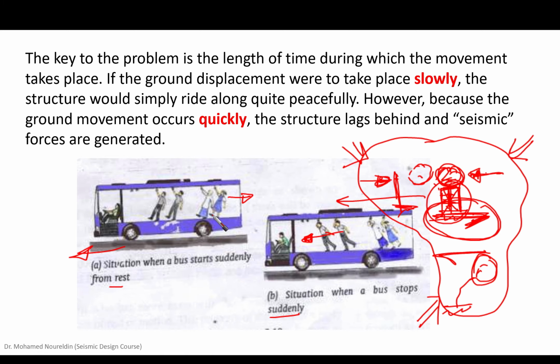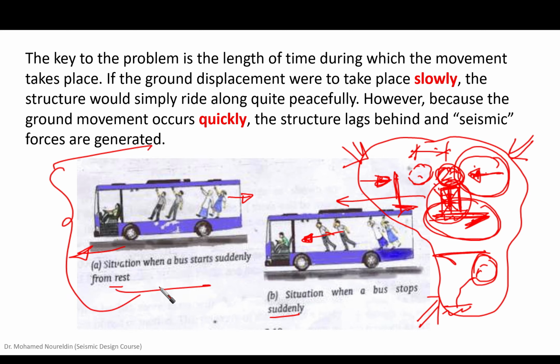We are going to have nonlinear displacement. Actually, whenever we apply the force in this way, this means that elastic force might happen. We're not dealing with any nonlinearity here, but we are going to consider nonlinearity by using some factors. Okay, so we're going to use some factors to transform the linear displacement that is going to take place to a nonlinear one, as we are going to see in the details. Okay, so if you understand this concept, this would give you the idea of the equivalent static force method.